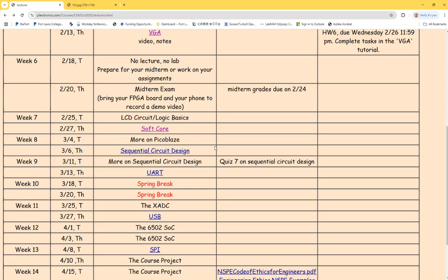And a lot of times, you can purchase the more advanced FPGAs from Xilinx, Altera or Intel right now, which have hard cores in them, like ARM cores or other different cores. It's not like a soft core you program, which will probably have more time delay but more flexibility. But there are a lot of other issues as well. So there could be a hard core in it, and you can directly design the peripherals, the digital blocks, and make the connection to the hard core, and then use it for a specific application.